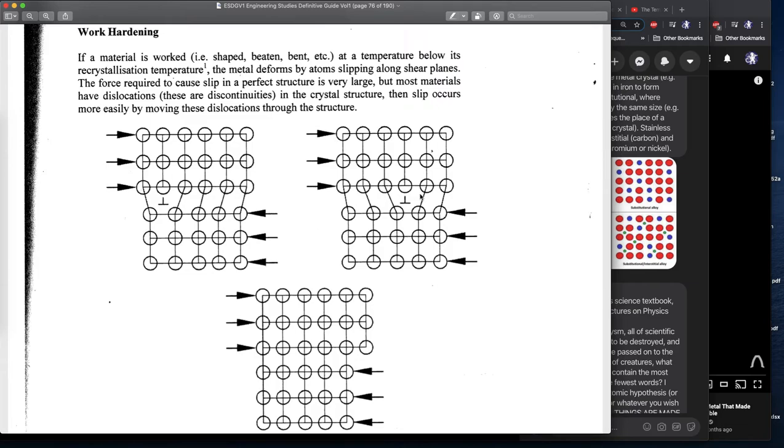And what happens is they can slip. It's like if you've ever covered your textbooks or your workbooks with contact. Have you guys ever done that? And seen how you can get bubbles in the contact? And you know how you can move that bubble around the contact? Okay, well, the same thing happens with metal crystals, that we can move that bubble around the crystal.